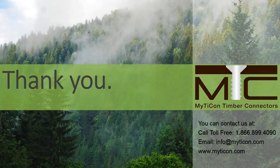This next one is about the extended Johansen theory. Is the extended Johansen theory available to North American design standards, or is it only applicable for use with EC5? I did touch on this in the webinar, but I'd like to explain why I believe it shouldn't be used yet. Some of the parameters are a little bit different. Some of the assumptions made in the yield models are a little bit different between the codes. And so you shouldn't assume that the embedment strength in one code is directly interchangeable with another one.